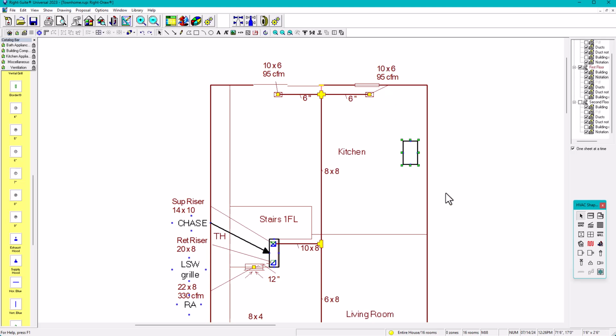Okay, so now we need to exhaust this. So this is obviously gonna be the side wall. So I'm gonna exhaust it right here, and then I'm gonna put a side wall cap. So in that case, maybe I could put this symbol right there. There we go. Just trying to use the symbols. So again, this is going to be a backdraft damper, and depending on the CFM, the manufacturer is going to tell you what is the actual size of this duct.